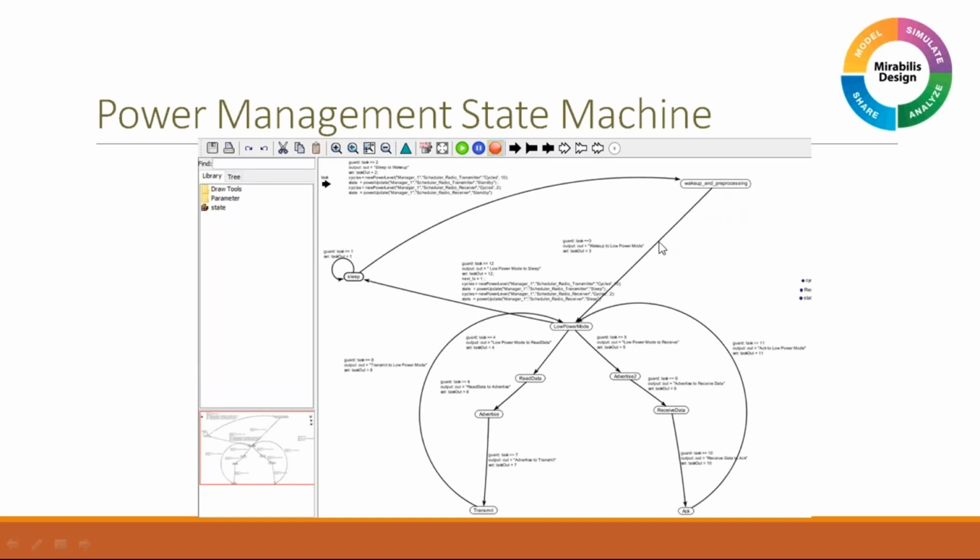And then on receiving a particular task, you may push that device to a low power mode, and based on the kind of activities, for example transmission or receiver, you can select the kind of cost or the kind of power overheads that you would be going through. For example, in this case, I have low power mode to advertisement mode, and then you receive the data and then go to acknowledgement. And this loop can go on based on the kind of activities that are happening in the platform as well.